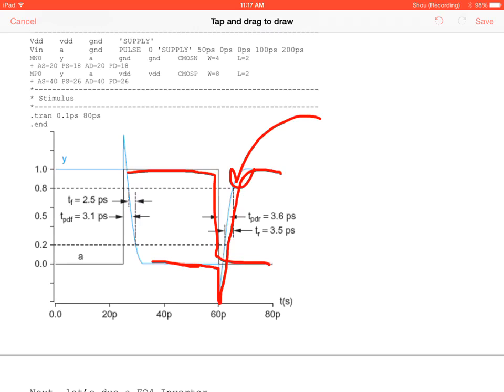So this is where understanding the physics comes into play. I wasn't just doing that to torture you guys, because you understand now that we have created an overflow of current here that's flowing to the ground. Here it's flowing to VDD, so you're creating a higher output spike. Here it's flowing away, so we're actually getting negative voltage. We've now created an instance where the circuit is flowing in the opposite direction of what we want, which is why we have to account for these rise time and fall time delays.